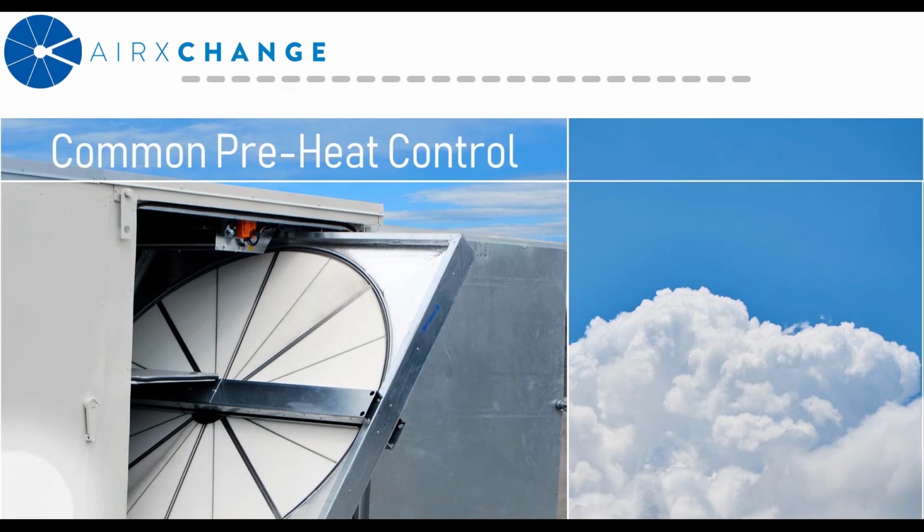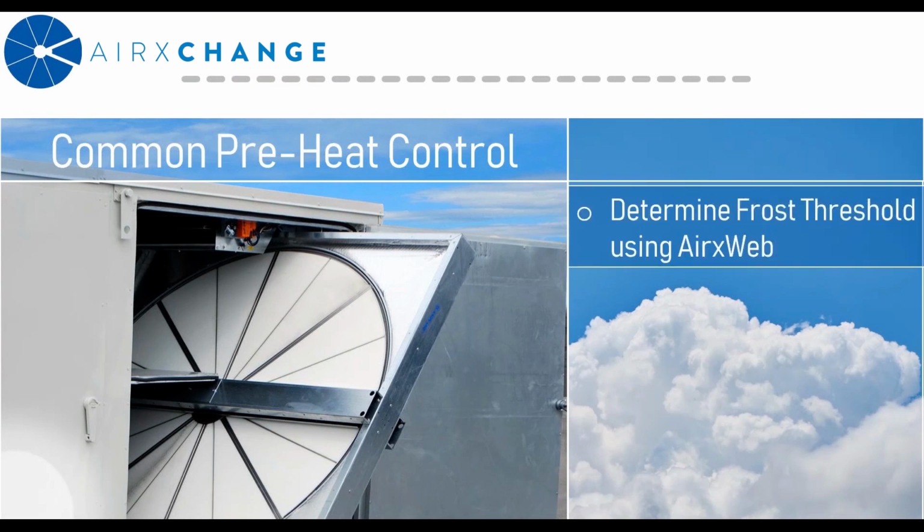So now that we've discussed the theory behind preheat, let's talk about the practical application and integrate that into a control scheme. First, you have to determine if your system is subject to frosting. And if it is, what is the frost threshold point and what size should your heater be?